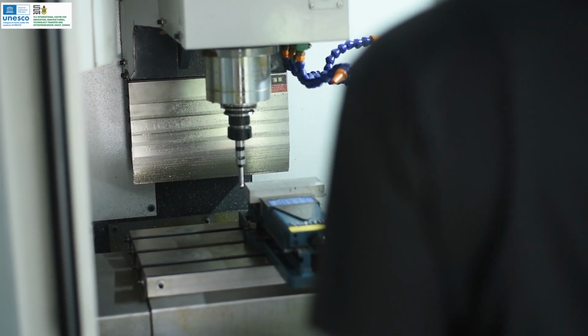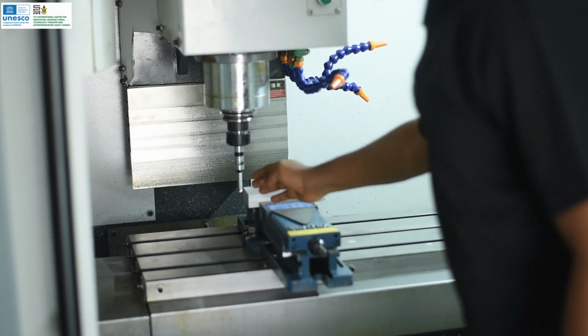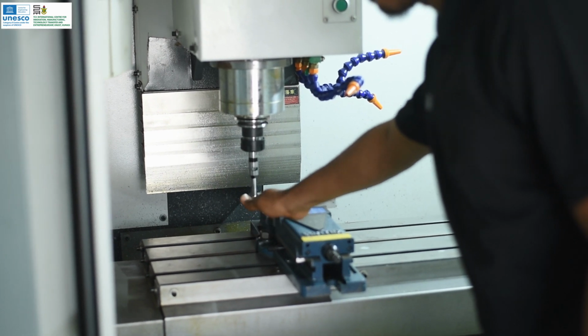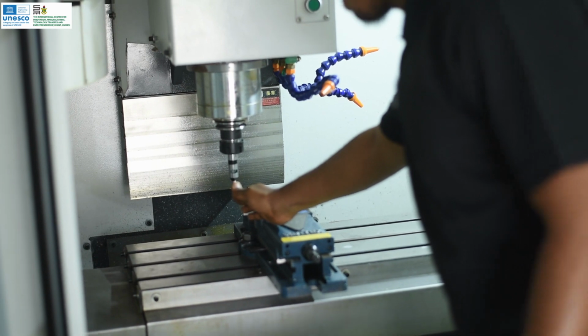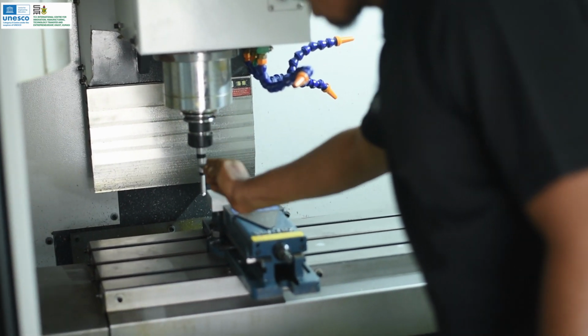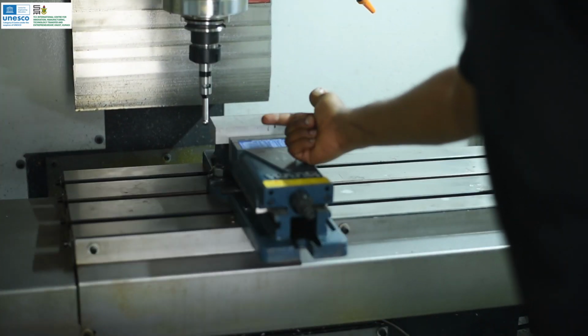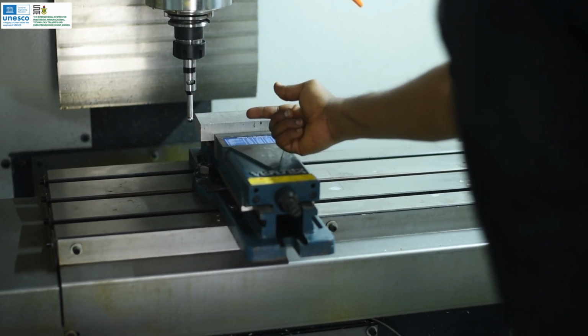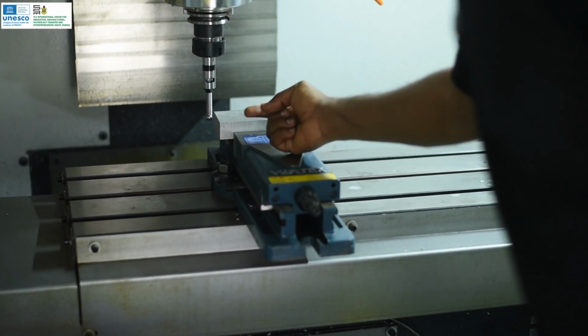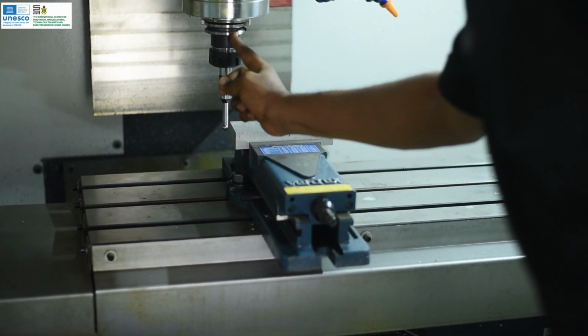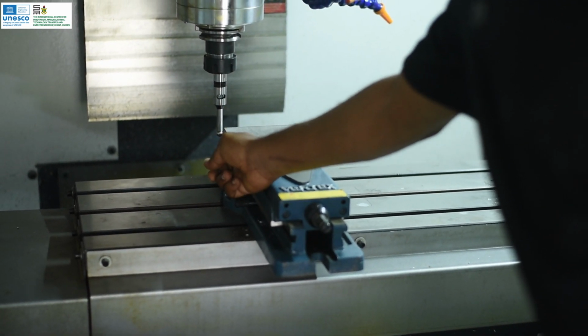Right. So assume we were here, and this workpiece was touching the edge finder. To get to the axis, you would move in the left direction, or x negative. That would bring you to x -5, the exact axis of the machine.